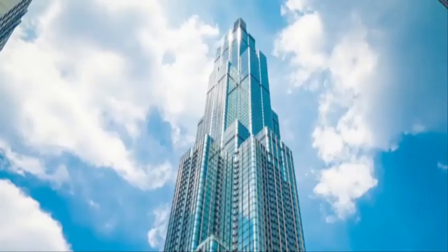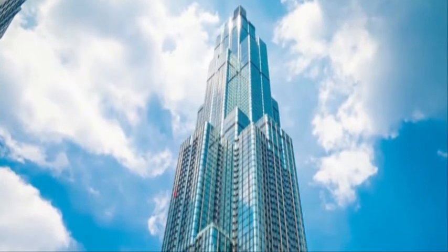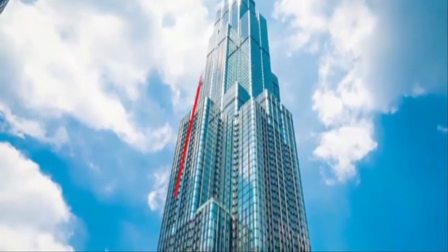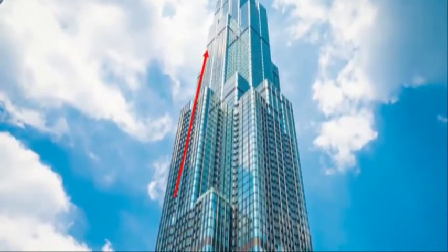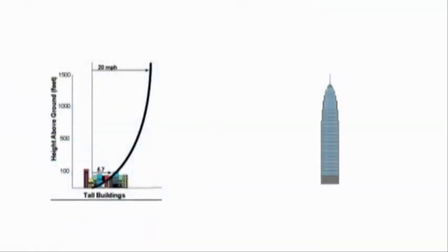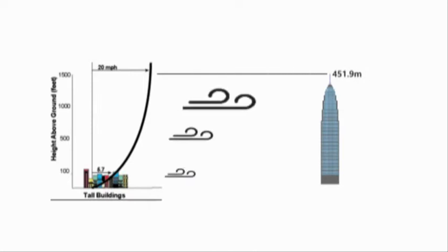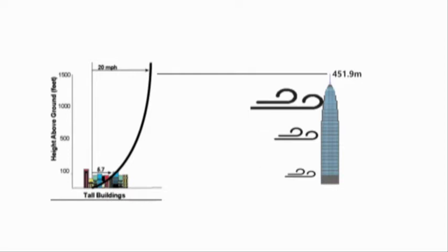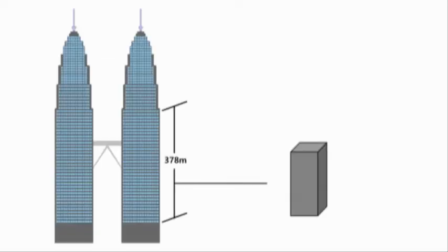Next, tapering and setback. Looking at the shape of many skyscrapers, including the Petronas Twin Towers, you can see that every one is getting thinner as they go up. These structures are called tapering and setback. In the case of skyscrapers, the wind load increases rapidly as you go up to the upper part of the building. So many kinds of high-rise buildings, including Petronas Twin Tower, use tapering and setback for the stability of the building under high wind load.